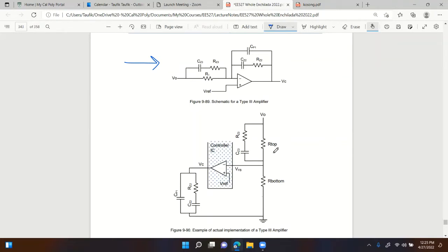So when you select the voltage divider while designing DC to DC converters and you close the loop, make sure that you pay attention to R top. Make sure that the one that's going to be fixed is R top. Because remember, in EE411 or 410, I don't remember which one now, you should get a good enough ratio to give you a very accurate output voltage sample.